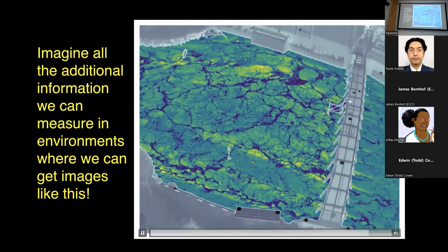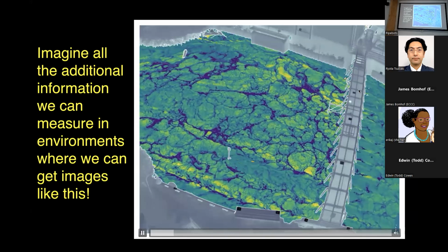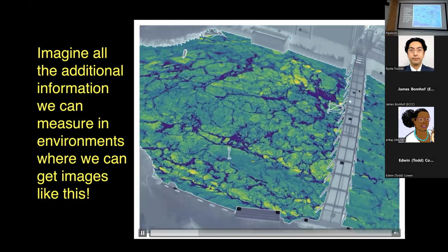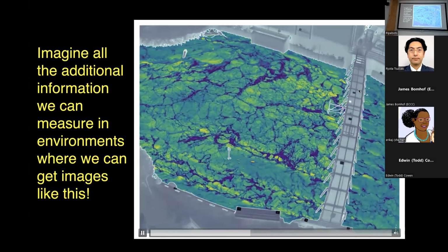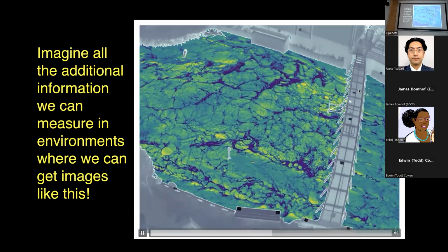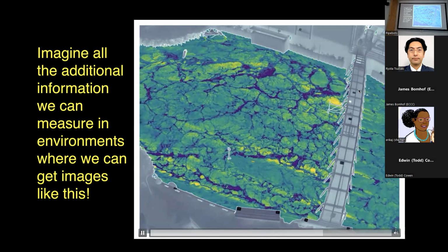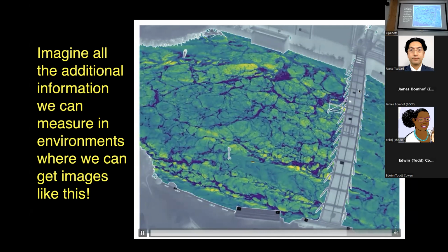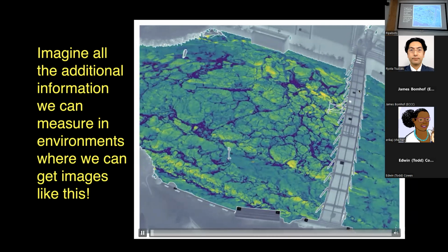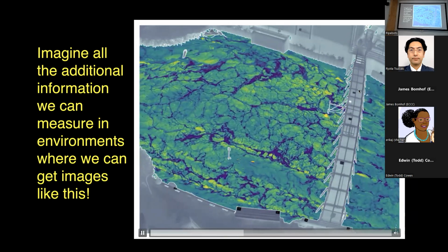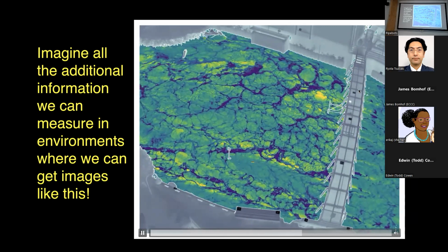The holy grail in gas transfer is understanding how much time a parcel of water spends on the free surface, what's called the surface renewal time scale, because the longer it spends on the free surface, the more it comes into equilibrium with the gas or the thermal condition. But once it saturates to its Henry's law gas concentration or thermal equilibrium, then until it gets stirred into the bulk, it's just sitting there, not efficiently transferring heat or gas. Then the turbulence comes up and stirs it out, and I get a renewal event. So it's pretty well understood.